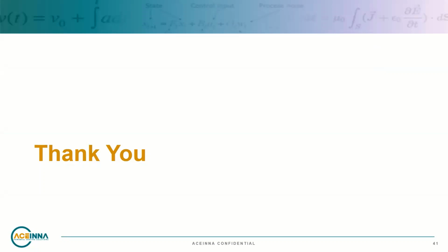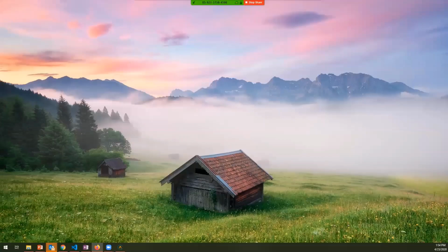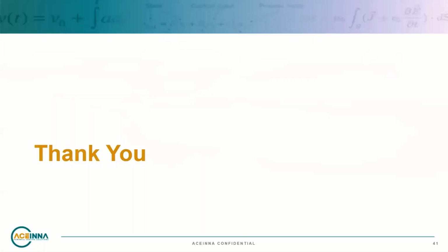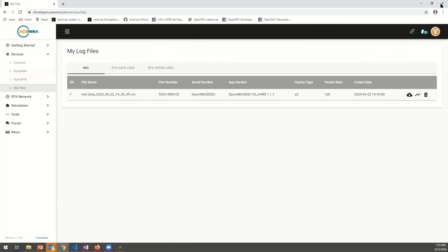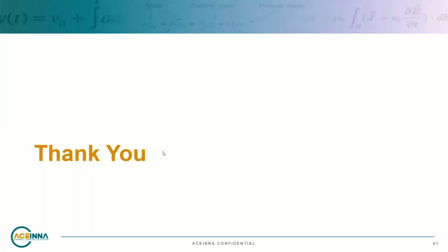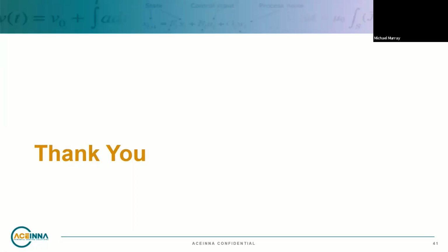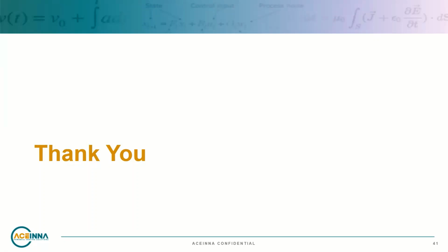Yeah, I can take that one. So in terms of OpenIMU300RI, we have two interfaces, the CAN and RS-232. If you have different applications where you have different sensors connected to the CAN bus, and you want to connect the OpenIMU to the CAN bus, we do have the CAN interface, and in the Visual Studio Code development, we give different applications and source code, where you can tailor them to your CAN messages and to particular needs and applications.